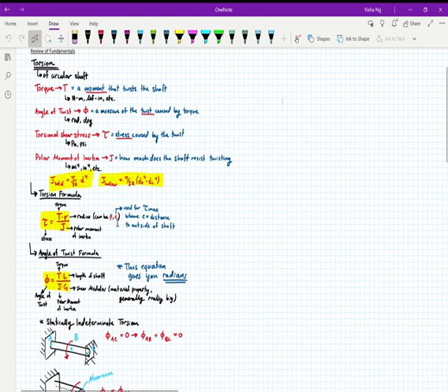These are all just different variables that mean R, radius. C in particular is used for tau max, where C is the distance from the center of the shaft to the outside of the shaft, because your shear stress is always biggest at the outside of the shaft because that's the part that's getting twisted the most.